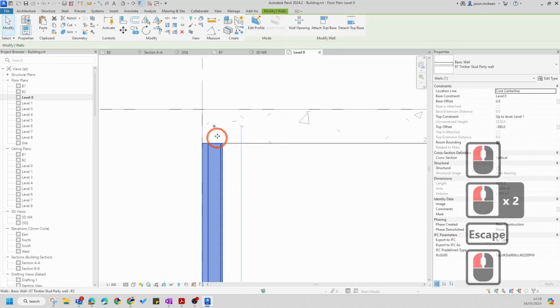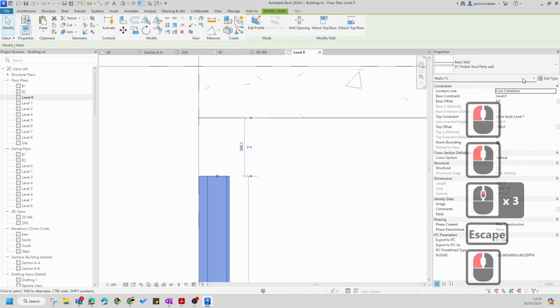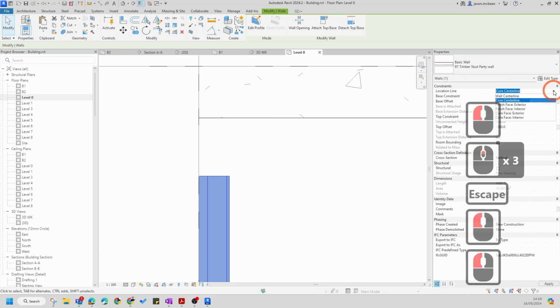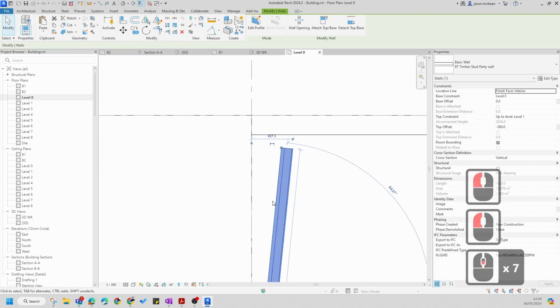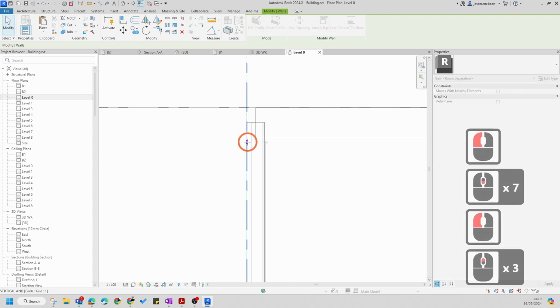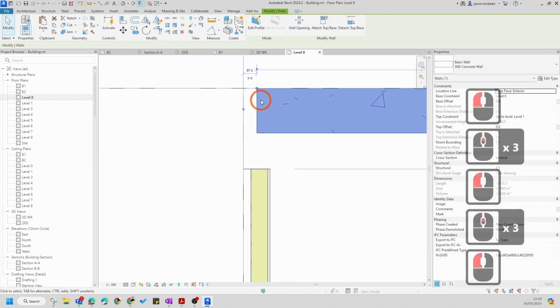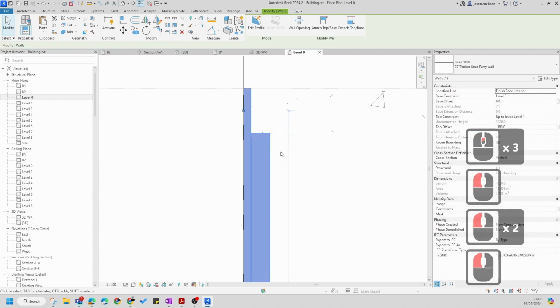Now what this does give me, this now gives me a wall. So if I select this wall, I can tell this wall it must behave in a certain way. So I'm going to say core finish interior. Okay, so finish interior. Now you can see the grips of the wall work on that layer. So now if I want to show my party wall in that direction, sorry, this wall must go past. That's the problem, it's trying to join. So this wall must terminate here.